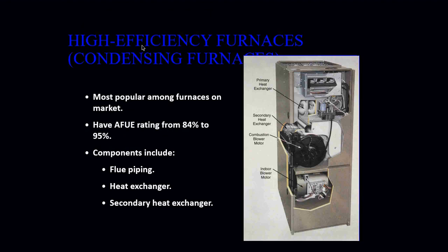Your high-efficiency furnaces or your condensing gas furnaces are really what is on the market today. Because, again, we want energy efficiency. Those are going to have an AFUE rating of anywhere between 84% to 95%, if not more. Okay, those components are going to have your flue piping, your heat exchanger, and your secondary heat exchanger. The secondary heat exchanger can be found down at the bottom.